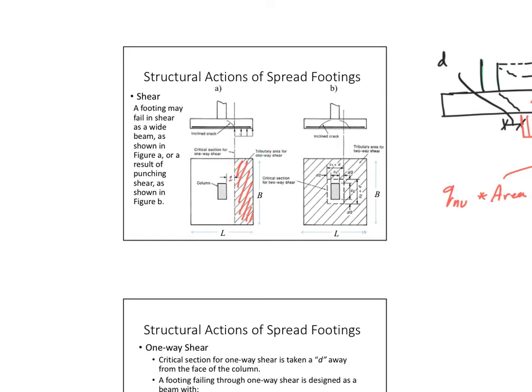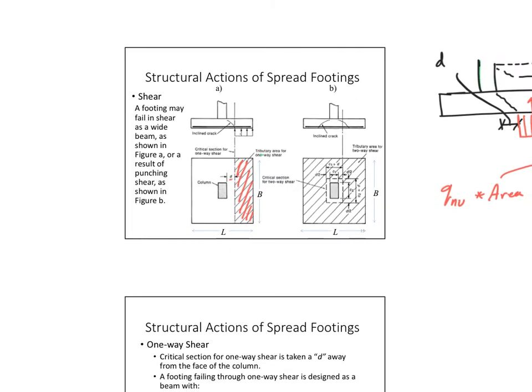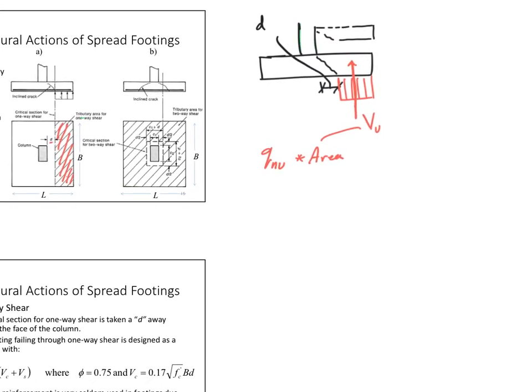And so this one here, if I want to calculate this area, it will be my L divided by 2 minus my C1 divided by 2 minus D. All of this times B. Okay? Think about it or do it the way you like. Just take the numbers and you will see that it ends up like this. What is C? Column side.